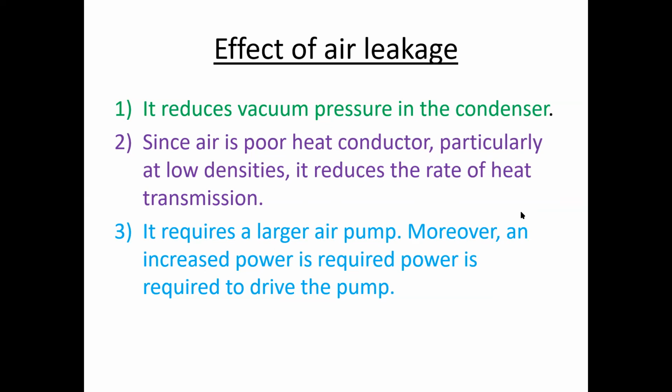Also, third point, it requires a large air pump. If there is more air in the condenser shell, a large air pump is required to extract that air from the condenser shell. Moreover, increased power is required to drive the pump. Okay, so these are the various effects of air leakage into the condenser shell.